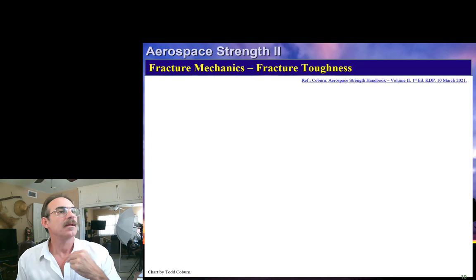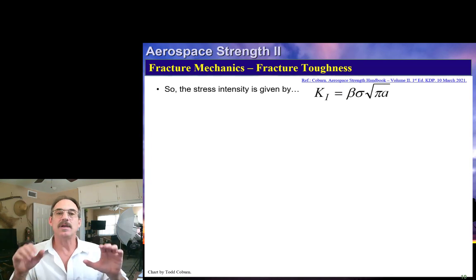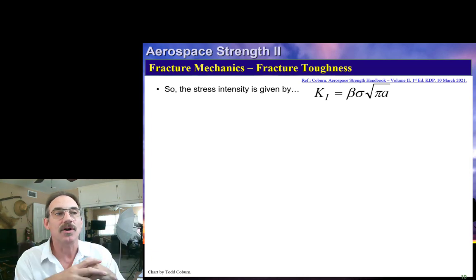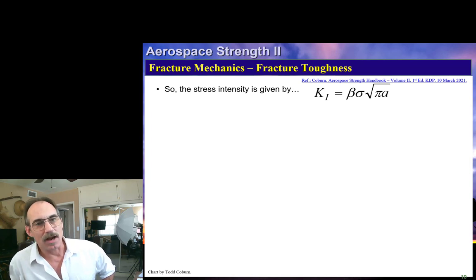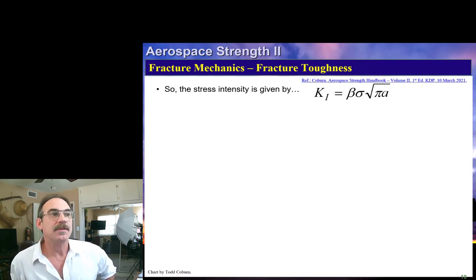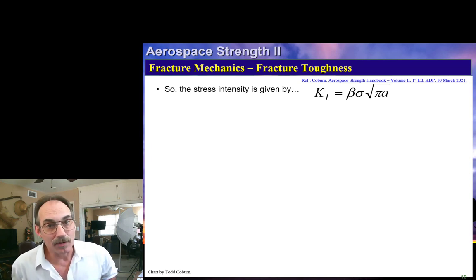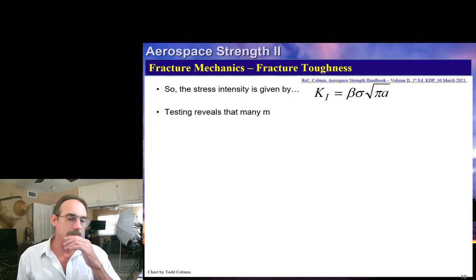Okay? All right. So with that said, now that we understand how to calculate K1 for the part, we're now ready to learn about what is the critical stress intensity. So we've now seen that we can get a pretty good estimate of K1, our stress intensity, for any loading and geometry by finding the correct curve, calculating the beta, figuring out what A parameter is valid with that curve, and calculating our stress intensity K1.